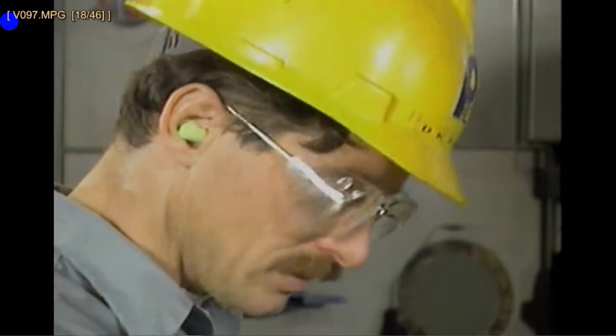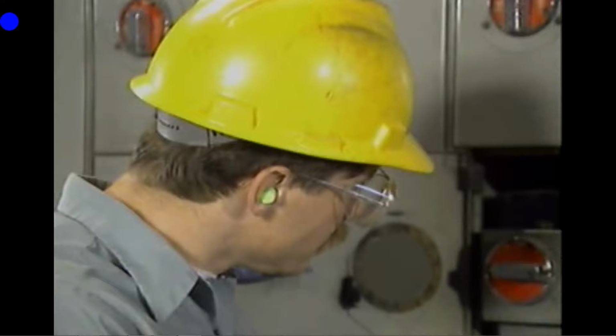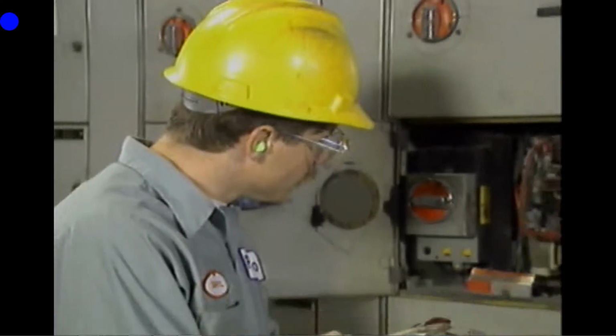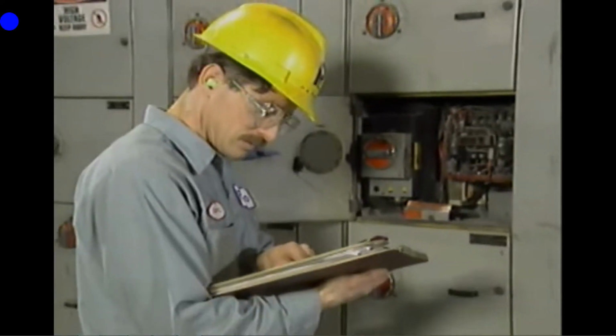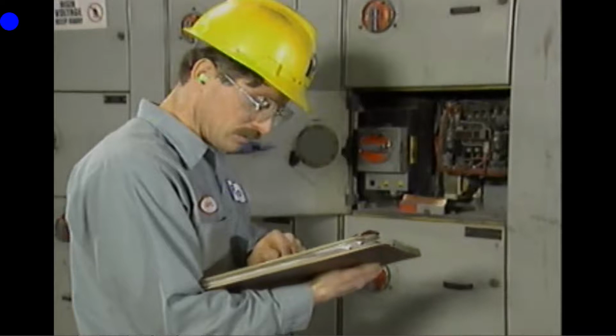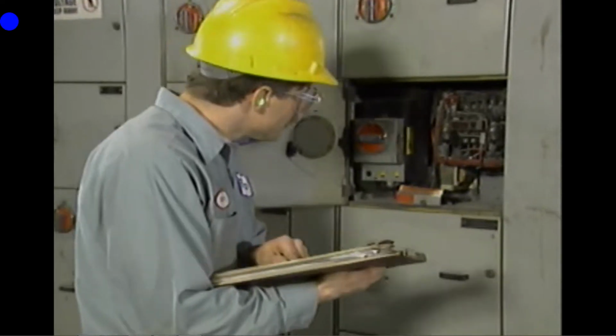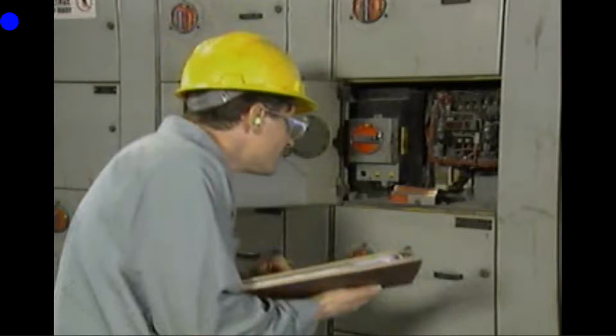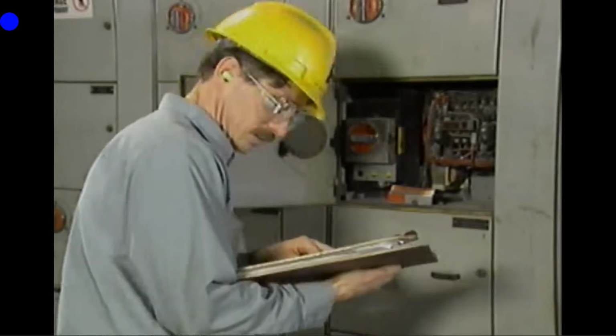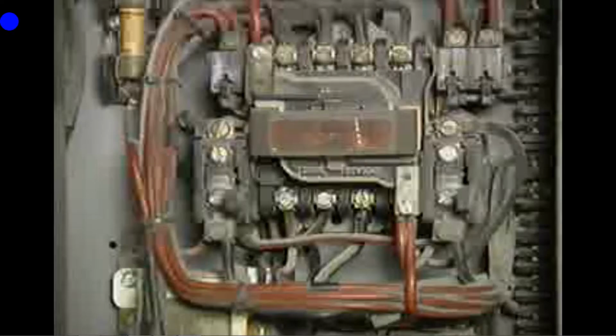During an inspection, it's important to follow all applicable safety precautions. You can usually begin your inspection by using your senses of sight, touch, and smell to thoroughly examine the controller. You should look for anything out of the ordinary, such as dirt, burnt insulation, broken wires, or loose parts. An unusual smell may indicate burnt insulation, and a hot spot may indicate overheating.